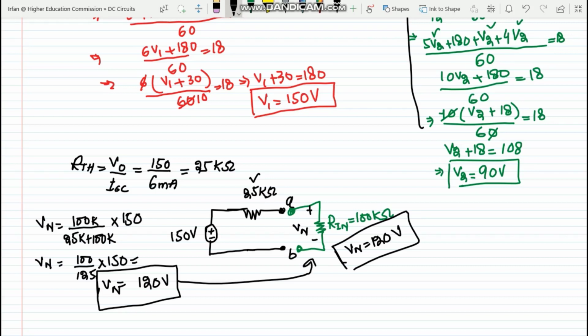So in order to make it the same as the open-circuit voltage, we have to make this resistance infinite, and it is very difficult for us to make it infinite. So then we use some source transformation method, or another method which is the decoupling method, by using a transformer or the common collector configuration, or another device we have is the operational amplifier, which shows these two terminals as infinite input resistance.